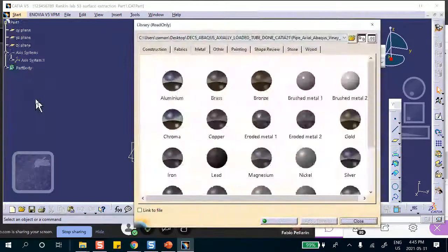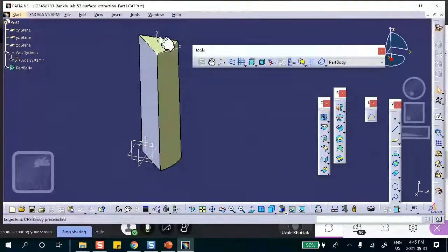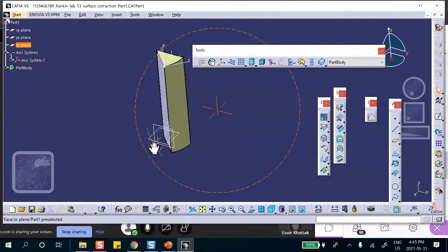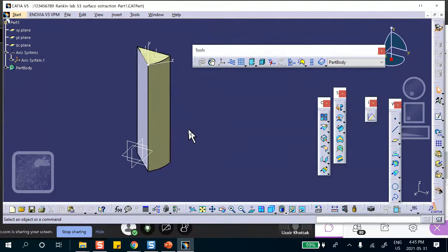Hey, Professor. Yes? Question. Why do you need a new axis when you can just use the global axis for the restraints? I can't do it for the other side. The other one is at 45 degrees. If this was 90 degrees, it would have been okay. But on purpose, I rotated this thing by 45 degrees so that this is not global anymore. Global does not have its x along that line. This one of the edges is okay, global, but not these two edges because they're at 45 slant at a slanted surface. Oh, I see. That makes sense.